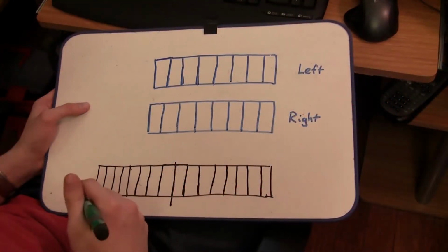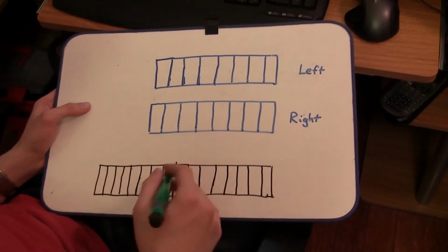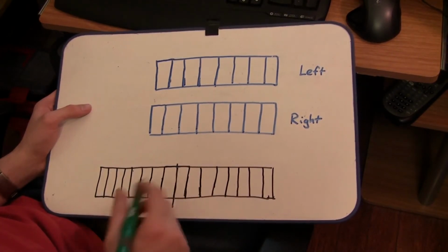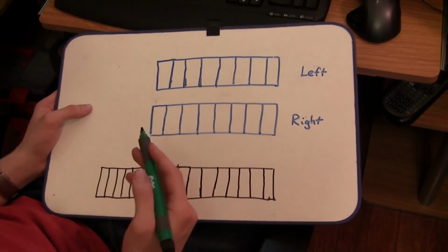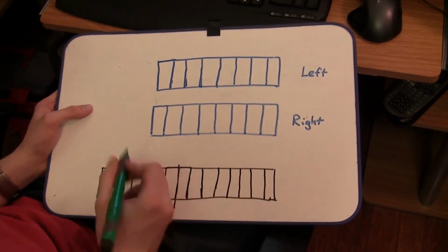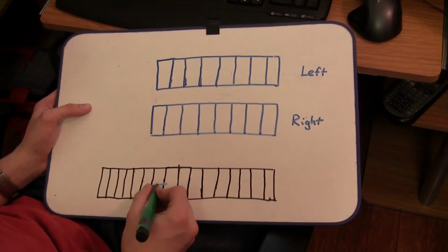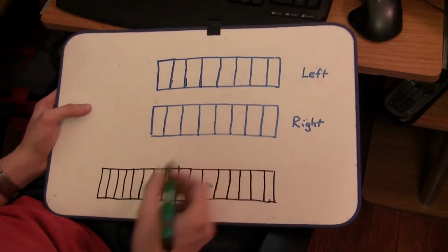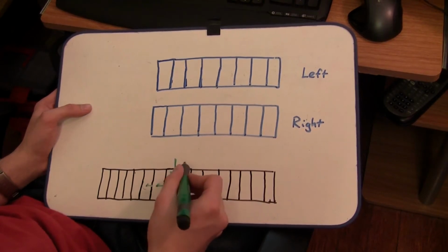For the last step here, we're going to try to make this a lot cooler. What we'll do is we'll have a left and right half of the LED chain defined. The left 25 will correspond to the left audio channel and the right 25 to the right audio channel. What we'll do is we'll have on each sample the previous sample propagate away from the middle on the left and right side, and then we'll bring in a new sample into the middle.